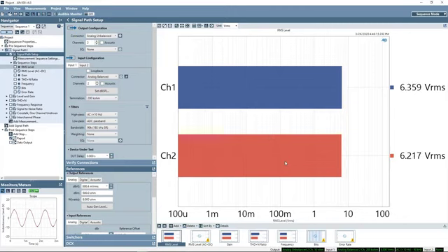As you may have noticed, the default APx project file contains the basic 6 audio measurements: level and gain, THD plus N, frequency response, signal-to-noise ratio, crosstalk, and phase. I'm going to enable all of them. When measurements and results are enabled, they'll be executed as the sequence runs.